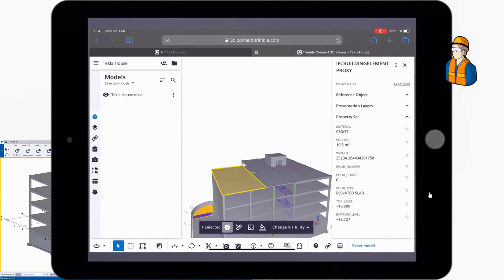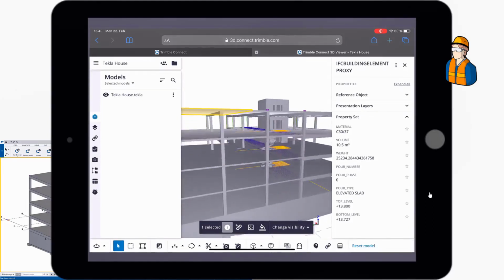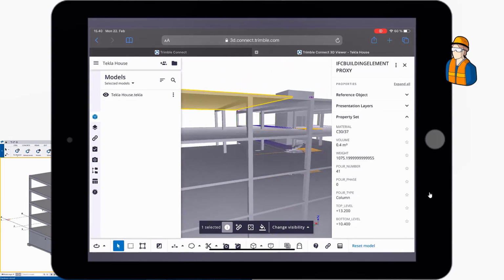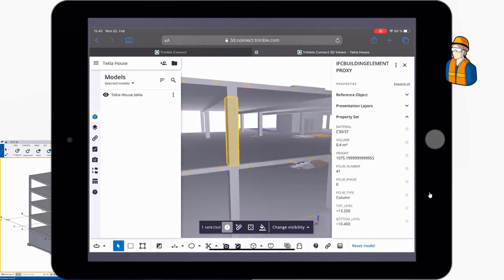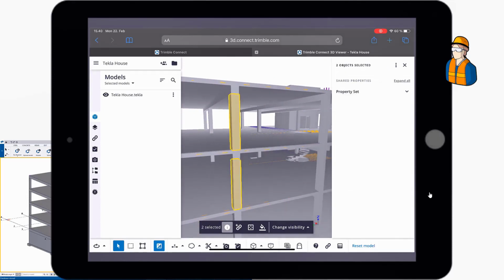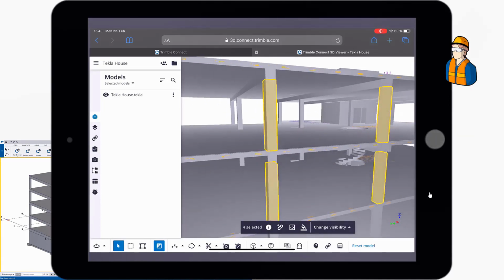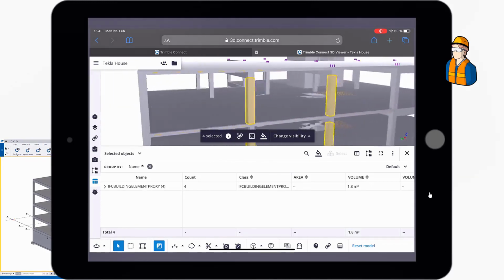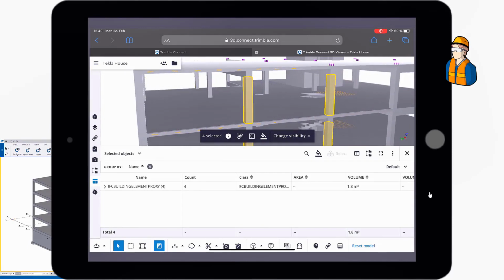And in Trimble Connect, if this is the first time you see it, you can inquire objects by selecting them and checking all the properties that have been uploaded with it. In this case, you can see the volume, the material, and some pore data as well. Alternatively, you can also select several objects, and using the object browser, you can then do cool stuff like adding up the volumes, for example, and inquiring those. Or you can build your own templates and columns and reports.